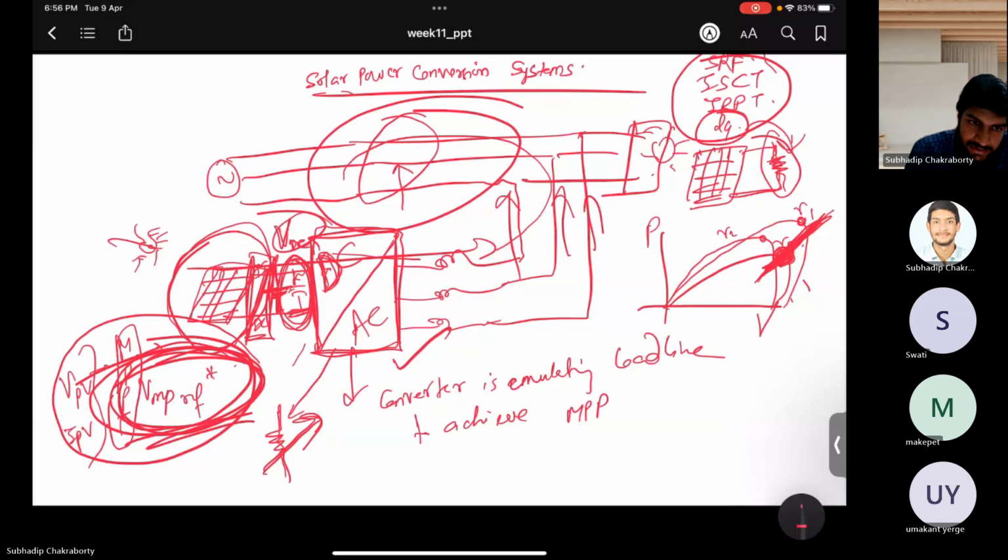So I want that. That converter will emulate it based on the control, and the battery is doing two things: maintaining the DC link of the DC-AC, as well as providing support. You may control the reference current such that some power is also stored in the battery, and during emergency times you can take the power out and utilize the stored PV power during night time. When the PV is not generating anything, you can use the battery to push power in addition to the source or supply, to support the loads and sell some power also. You can do that.